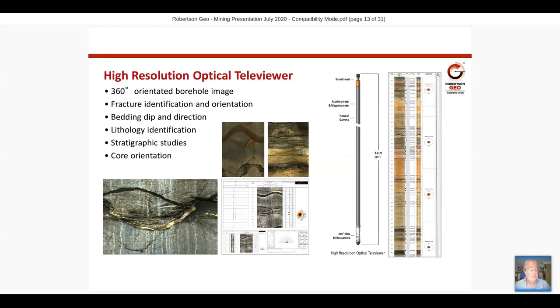So there are two main types of Televiewer currently in use, and obviously this technology has moved on dramatically in the last 10 years or so. And as a geologist, to get a picture of downhole conditions and the downhole formations is invaluable. You can see quite clearly the thickness of the beds, the degree of fracturing, some of the smaller features. You can see in that bottom left picture some infilled veins showing through there.